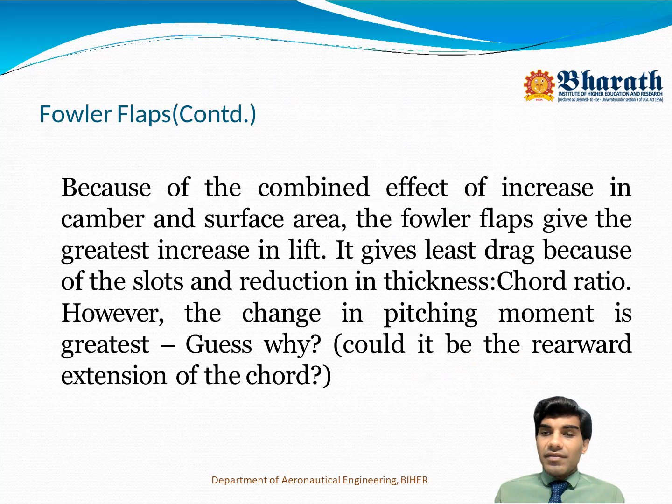So what exactly is given? Because of the combined effect of increase in camber and surface area, the FOWLER flaps give the greatest increase in lift. It gives least drag because of the slots and reduction in thickness. So this is a double advantage. It gives more lift and least drag because of the surface area and camber increase, and because of the slots reducing thickness. However, the change in pitching moment is greatest. Guess why? Because of the rearward extension of the chord. Okay, so this is the reason.